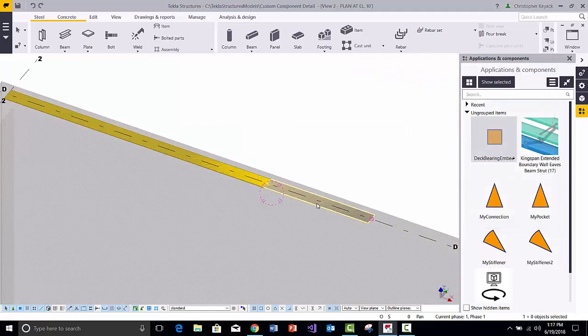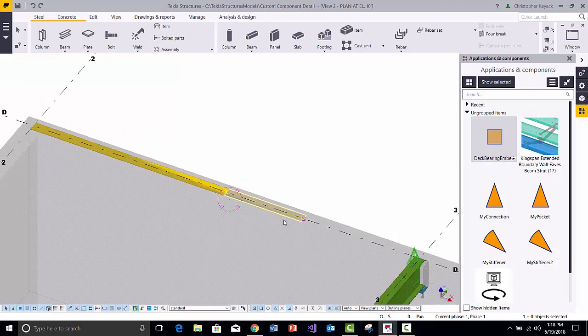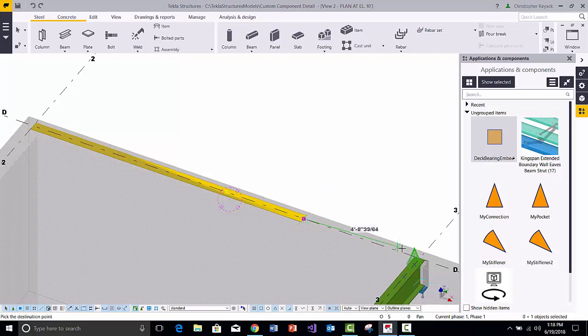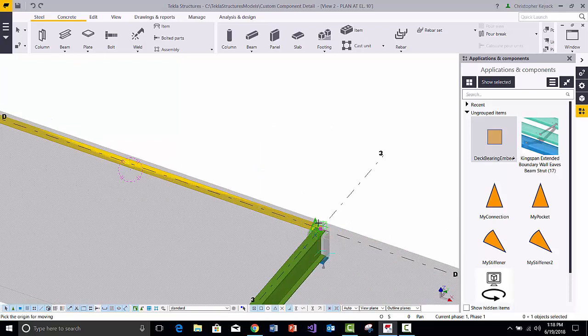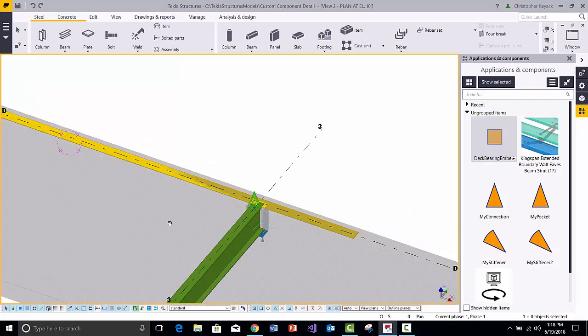you'll see here that now that second embed that was only 4 foot between the picking points, the plate now matches that. And if I grab this, I actually stretch it across a little bit more, you'll see that it changes. And if I actually make it greater than the 10 feet, then it will also do that as well.